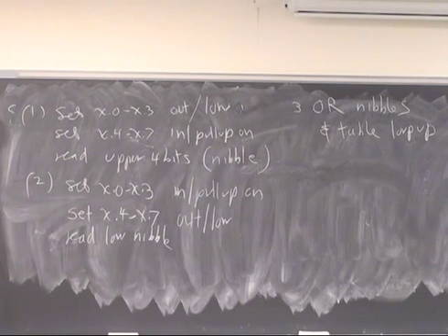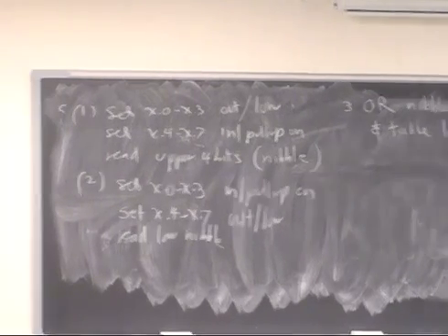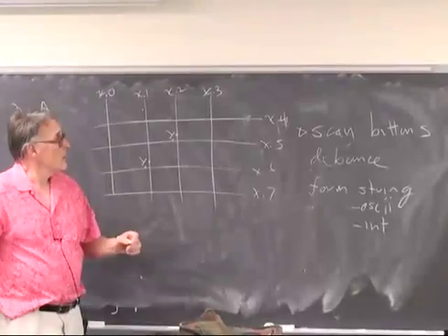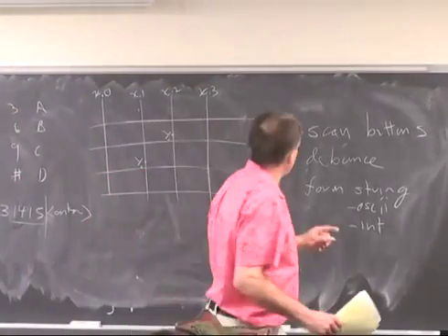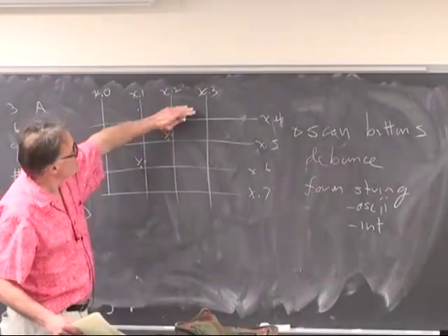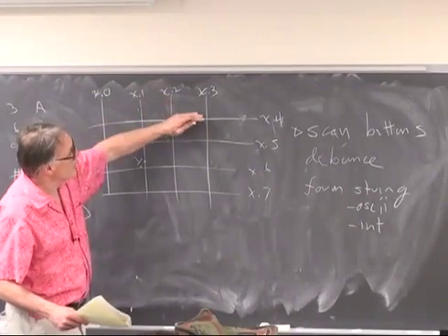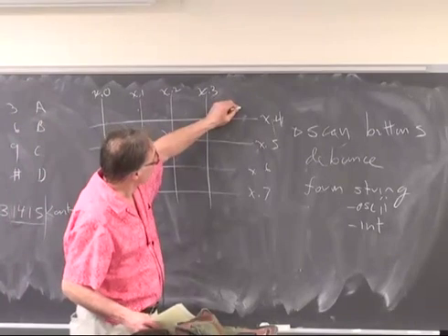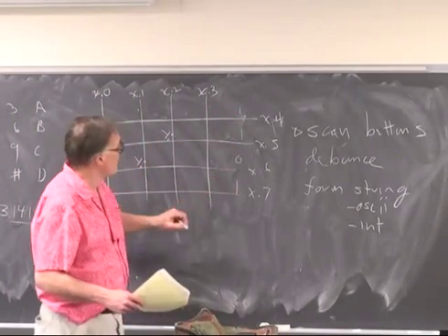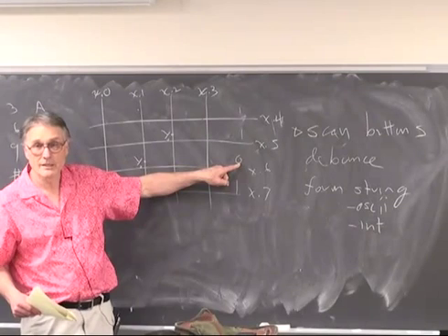For using this particular keypad in this situation, one button down is a valid button push. Two buttons down is ambiguous and should be an error. Zero buttons down is, of course, valid. So if exactly one button is down and these are all low, then only exactly one of these lines can be low for one button down.